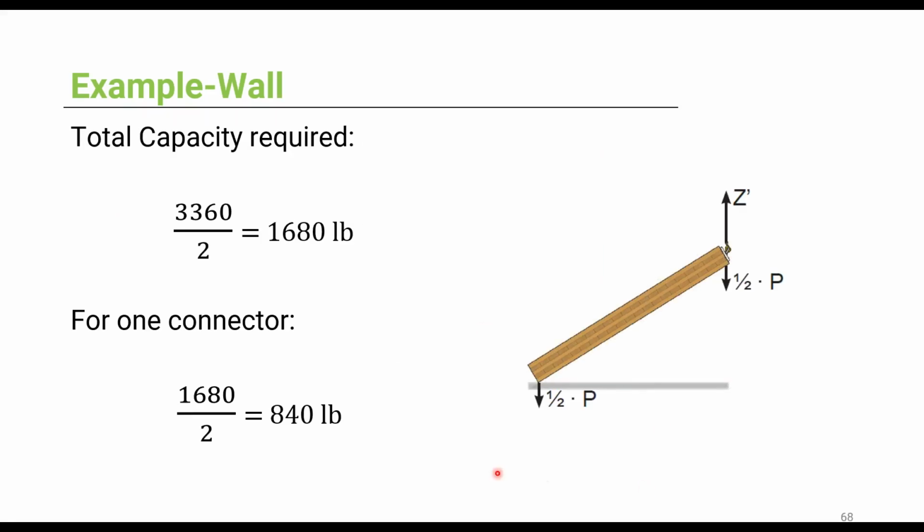This figure shows the weight distribution of the wall panel being lifted a little bit better. You can see that the anchors are only taking half of the weight of the panel in shear. When you lift the panel fully, the fasteners are working in withdrawal, and we know that they are much stronger in withdrawal, so we don't really have to worry about them after.